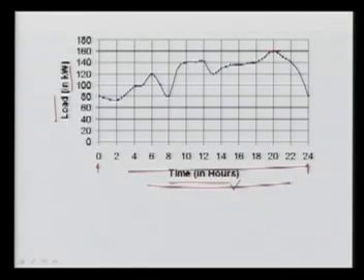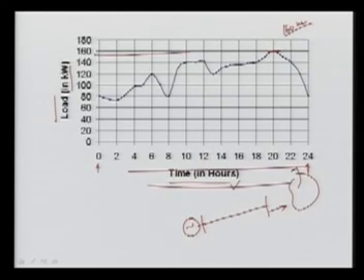As I already said, the capacity of generation should be such that it meets the maximum demand. Here this maximum demand is, let's suppose, 160, so 160 kilowatt is the load. Suppose it is an isolated substation fed by one generator. Here is your generator, then we have a transmission line, and this is your load with this variation. What will happen? Your maximum demand is 160, so the generating station must be more than that 160.